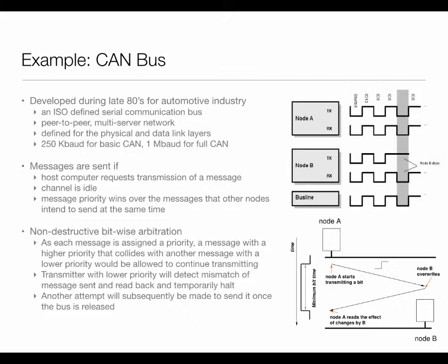So there's a notion of priority over the shared medium, and this is a bitwise arbitration that takes place. On top of it, you can make higher level scheduling algorithms. For example, by appropriate manipulation of priority, you can arrange for certain types of traffic to get priority. You can begin to control the delay that they are going to take over the network. All those kinds of things begin to happen.